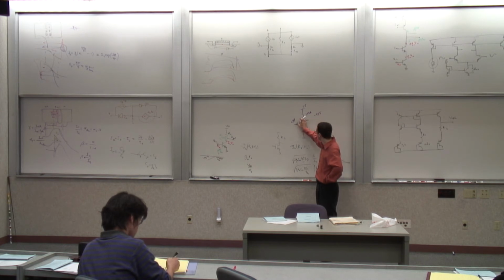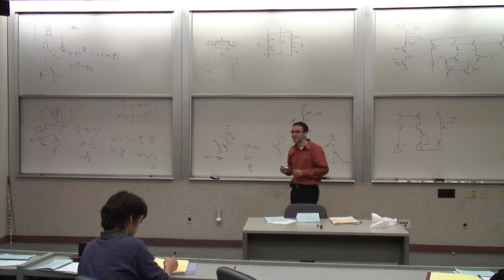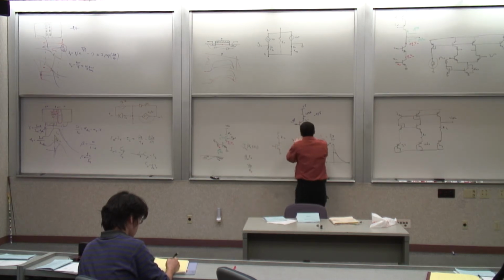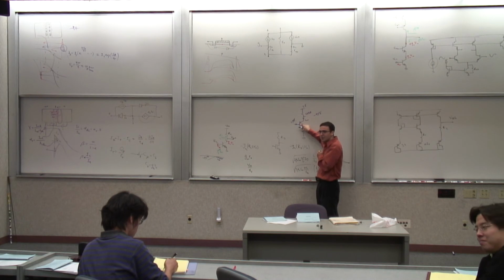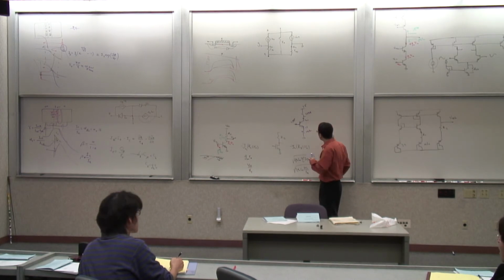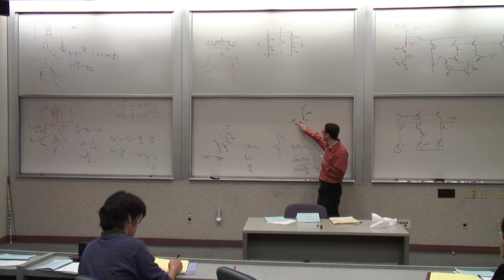So the voltage across here is something like 96.7 volts, right? Forward biased. That's one unhappy junction. So it is in saturation. Yeah, of course. That tells you that there's something wrong. This junction has been forward biased a long time before that. So I go back and say, okay, let's see what the actual voltages are. This voltage cannot go below 0.1 or 0.2, because once this gets forward biased, this will be 0.6 volts forward. So that means something like 0.1, 0.2.